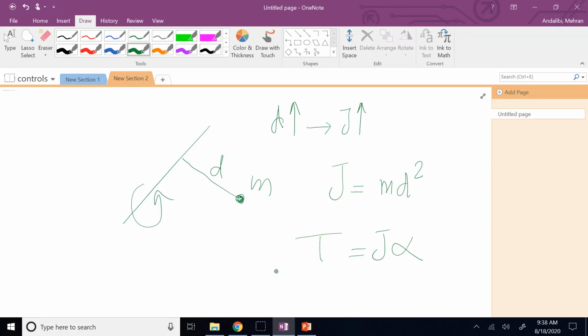It's a vicious cycle. The torque is going up because you are burning more and more fuel. If you keep J constant, right? If you keep this moment of inertia constant and T goes up, what does it mean? It means alpha goes up, and alpha is the angular acceleration of the shaft. The bigger it is, it means omega will keep increasing more and more, right?